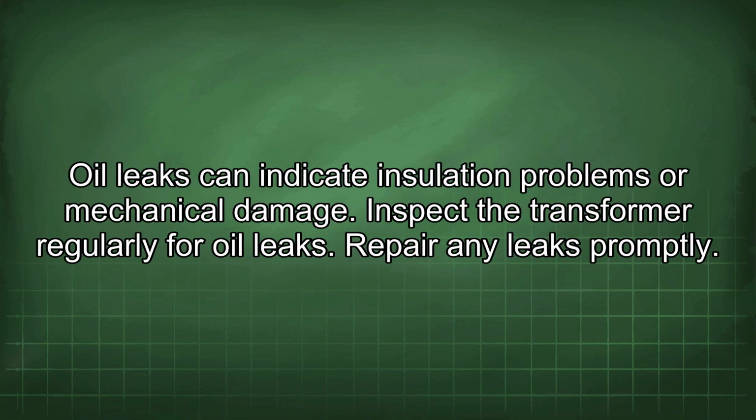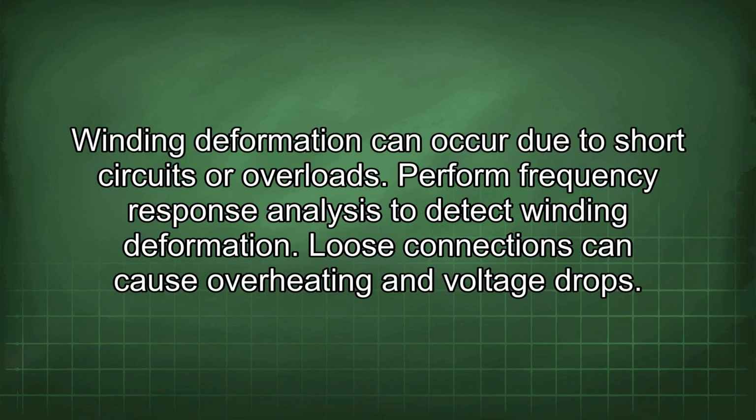Oil leaks can indicate insulation problems or mechanical damage. Inspect the transformer regularly for oil leaks. Repair any leaks promptly. Winding deformation can occur due to short circuits or overloads. Perform frequency response analysis to detect winding deformation.